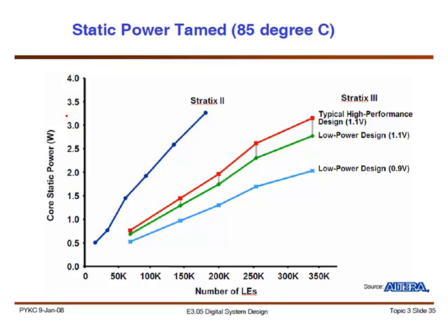And if you look at this, basically using these power optimization techniques in Stratix 2, as the number of logic elements goes up, so does your static power, right? But then by using these low power techniques of using the fast versus the slow logic elements, you can bring down the profile like this.